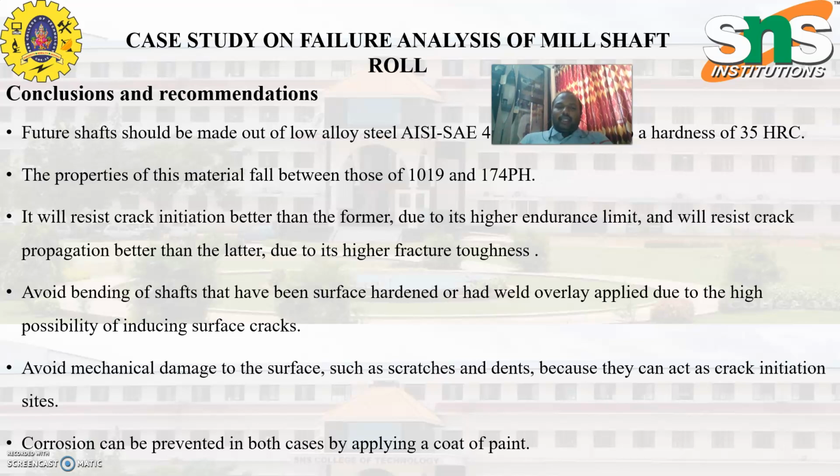Mechanical damage such as cracks and dents should be avoided, so that the possibilities of crack initiation become lesser. And the last point is that some coating or painting should be done after the weld overlay, so that corrosion will be controlled very much. Thank you.